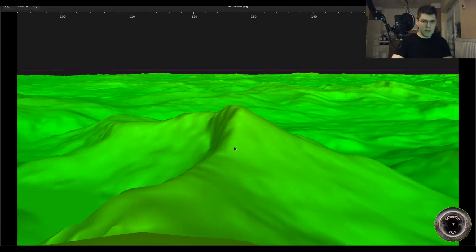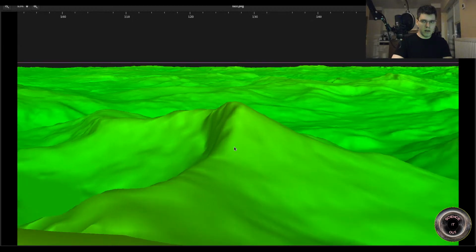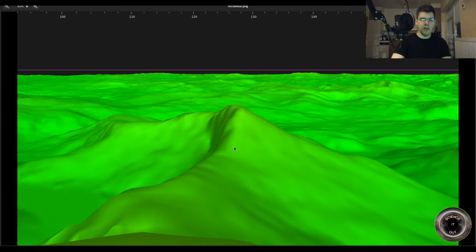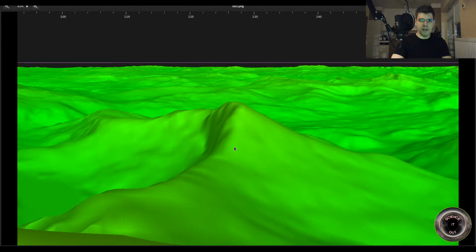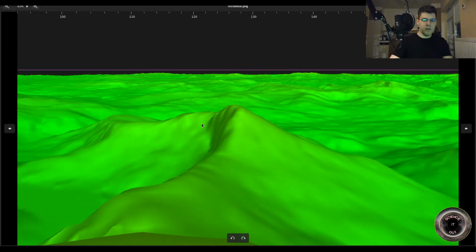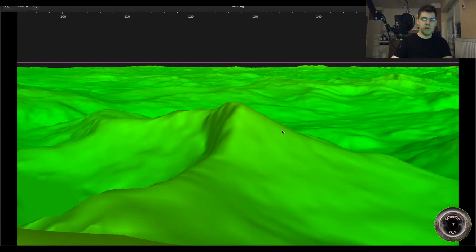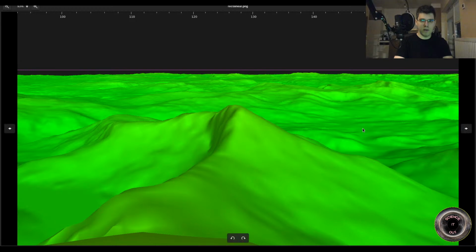So we get this, and you can see that if we switch between one and the other, there is a visible difference. Because this is already a fairly wide field of view. I think it's like 69 degrees. So it's large, and the small angle approximation doesn't work anymore, and so the fast generator is no longer as accurate. And if you compare these two simulations to the photo, the rectilinear is a much better match to everything. Initially I was wondering why I'm getting such a bad match to the photo, but then I realized this is a wide field of view. I need to use the rectilinear perspective to get a better fit. And this is quite a good fit to the original photo.